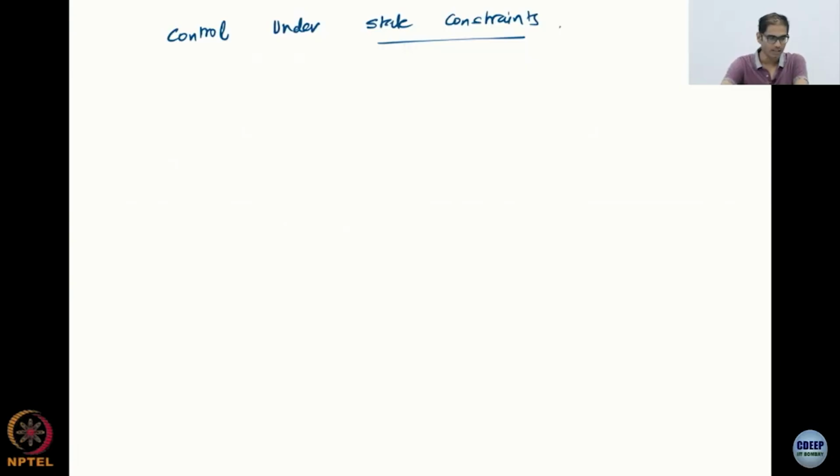So you can just blindly go and design a Lyapunov controller for your systems. Basic robustness, bounded noise, bounded disturbance, handled. You do not have to worry about it, great. But the other scenario is that of constraints on the control and constraints on the state, okay. Of course, I am not going to talk about control constraints per se, which can also be handled, by the way, using the same methods that I am going to talk about, but we want to talk about state constraints.